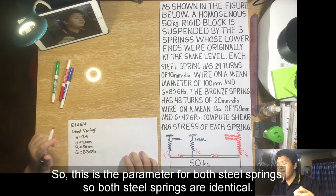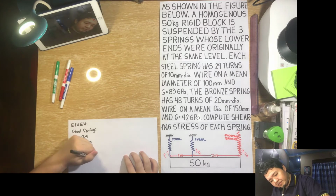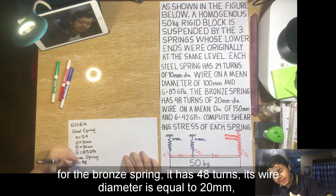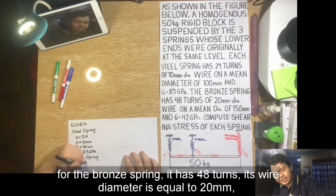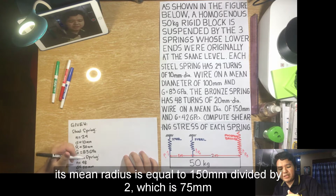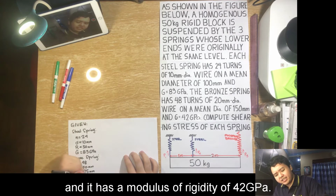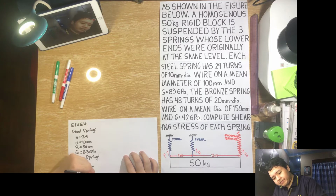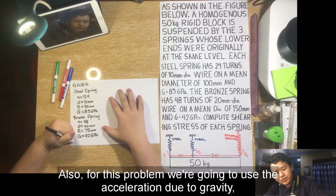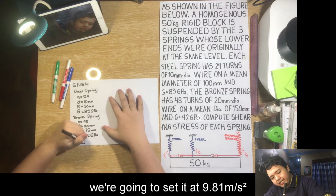Both steel springs are identical. Next, we have the bronze spring. For the bronze spring, it has 48 turns. Its wire diameter is equal to 20 millimeters. Its mean radius is equal to 150 millimeters divided by 2, which is 75 millimeters. And it has a modulus of rigidity of 42 gigapascals. Also, for this problem, we're going to use the acceleration due to gravity. We're going to set it at 9.81 meters per second squared.